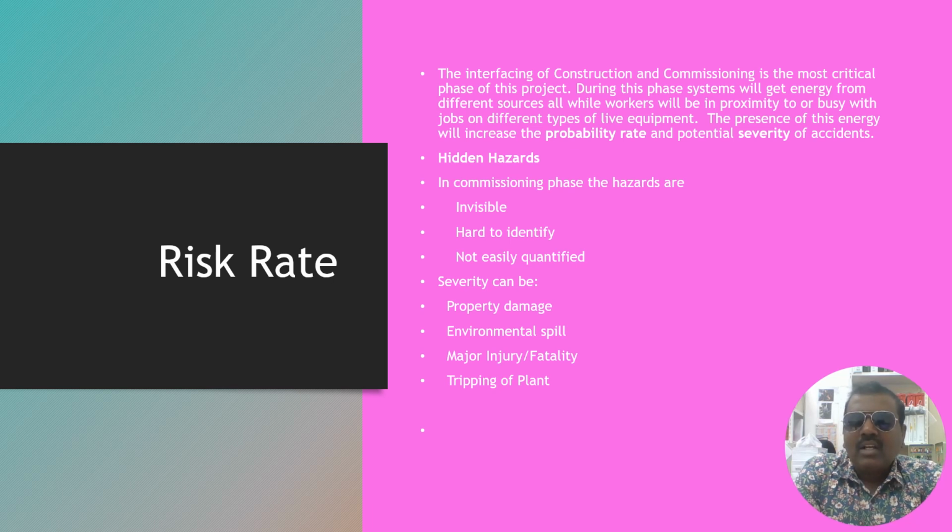In this condition, there will be 2-3 breakers with 2-3 different electrical circuits, from different electrical panels also, right? Because a shutdown or blackout should not affect the location.